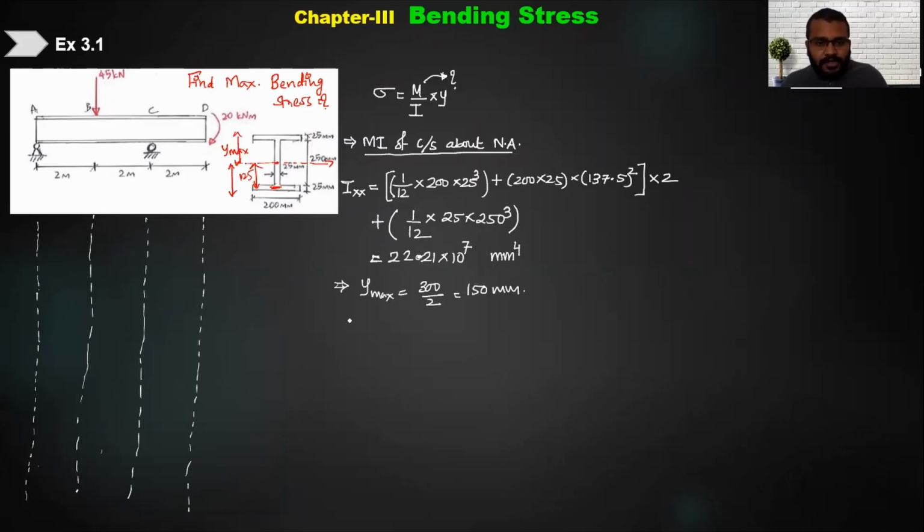Yes, Saurabh, tell me. Now, what is the first step we do? Shear force about point A, SF1 and SF2. The left side will be 0. Let me write down something. We are calculating the maximum bending moment M, which is the question mark here. So very first thing, do we require support reactions to be solved here? Along A and along C, yes sir. Yes or no? It will come, right? Yes, sir. So how will we solve this support reaction?